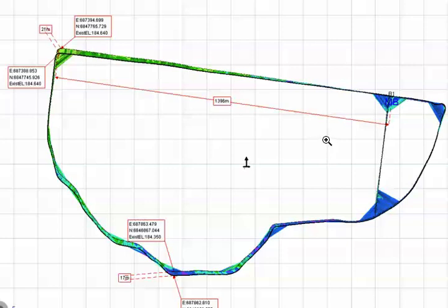And the other thing is, depending on how large your slopes are. If your slopes range from, say, just for argument's sake, a steep slope that's 10%, and at this point, say there's 20 meters out and it's sloping 10%, then you are going to be 10% of 20 meters, which is 2 meters. You're going to be actually 2 meters out in the vertical. So you can see that's going to be a massive amount of error.